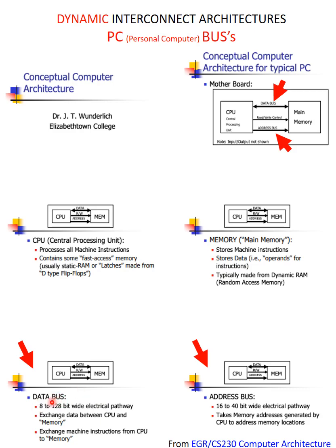Just in general, the data bus is as wide as possible. And you get on graphics cards, it's even wider than this because you want multimedia giant chunks of data. The bigger, the better. Address bus, there's only so much that makes sense because 2 to the 64 is a ridiculous number. It's just not a feasible amount of address space that would ever exist. So typically processors would have 40 pins on the back, so you could have 2 to the 40 addresses for your memory.